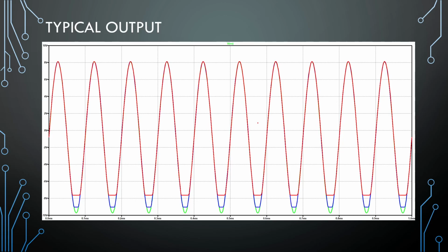Right, now the purpose of a Class A amplifier, Class B, Class AB, is to do some sort of driving. It is a power amplifier. Okay, so that is the amplifier that you get at the end before you have output to, let's say, something like a loudspeaker, whatnot. So it is basically a common collector or a common drain kind of setup, and your aim is to drive small loads.